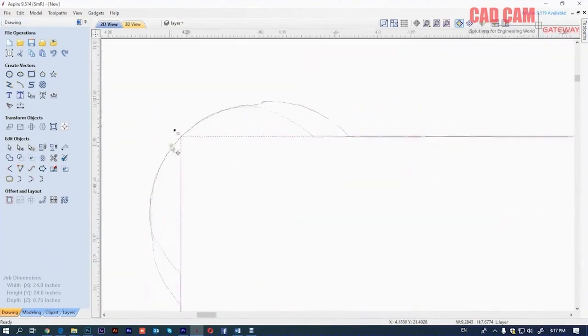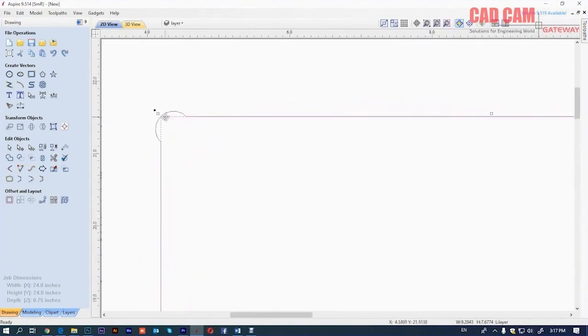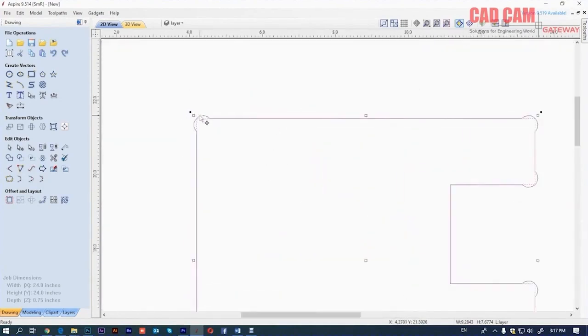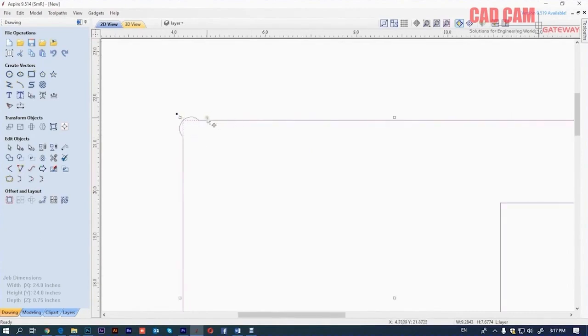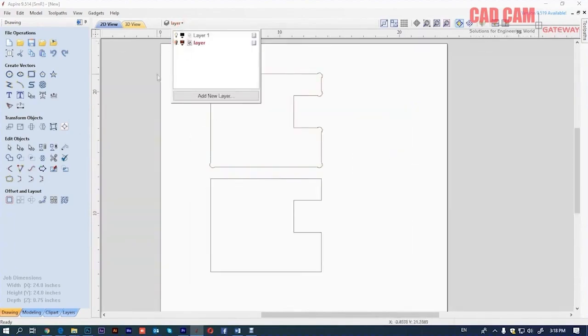Now pay attention, this part is very important. Even now our radius is still small, okay? And if I hadn't set the radius here, then when we do the cutting inside these pieces, when we cut the lower part of the job, let me turn it off and look here. Whatever tool we use here, the tool was creating a bulge. So we gave it this diameter so that the tool can go deeper from here. And when the fitting is done, the corner can automatically fit into it. All right, so I'll turn this off for a moment.